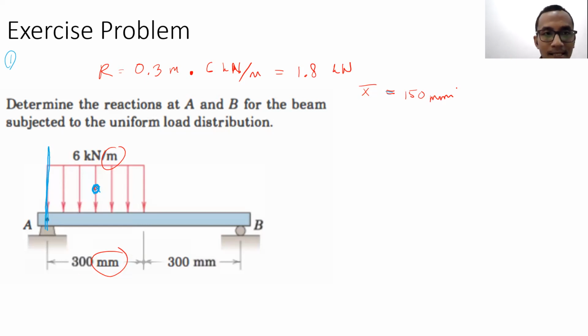Now, the next thing is we have to find the resultant force at A and B. So it's not yet finished. We know A is a pin, so there will be an Ax and Ay. And B, because it's a roller, it's only By. Then after that, we can use a moment at A or at B. No, you skip one thing. You're supposed to draw the new free body diagram.